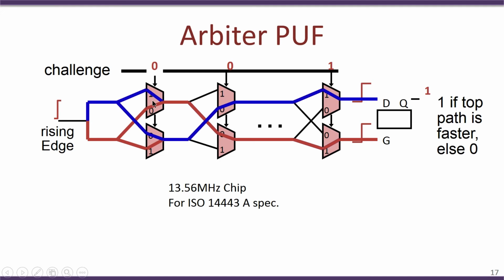There are essentially two aspects that make this design interesting for use as a PUF. The first is the fact that these signals, since they are propagating through all of these switches, due to the nanoscale variations in the design of these switches, these two lines, the red and the blue line, would attain a different speed of transmission. As we saw with the ring oscillator as well, the delays provided by each of these multiplexers are influenced by the manufacturing processes and the various intrinsic properties of the silicon and the process.